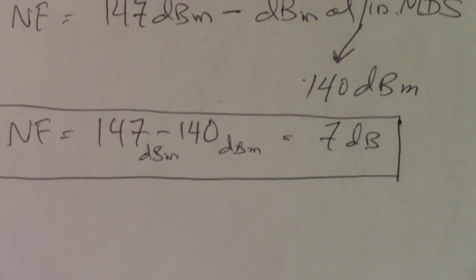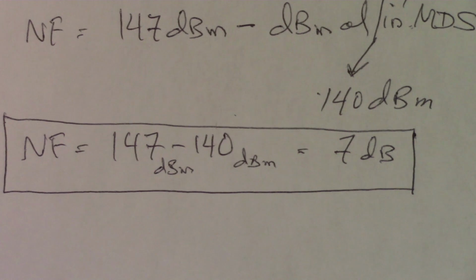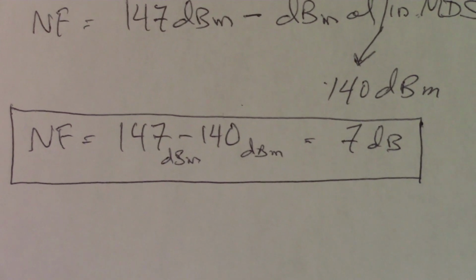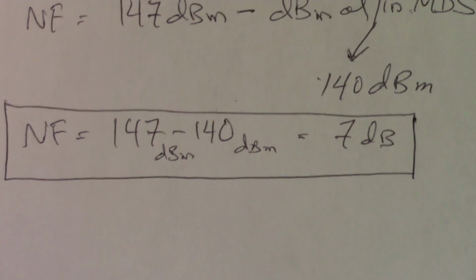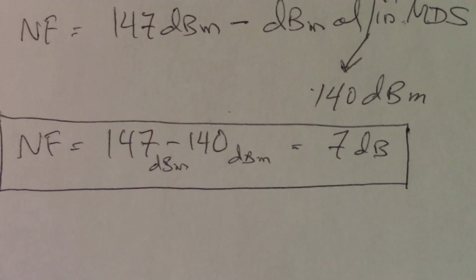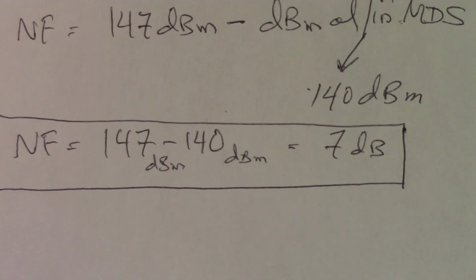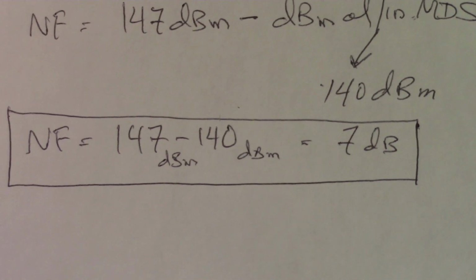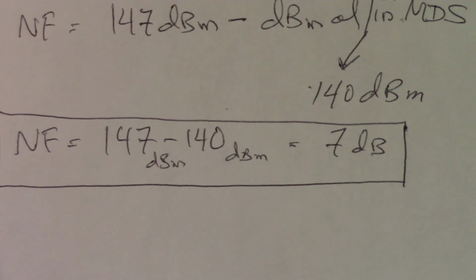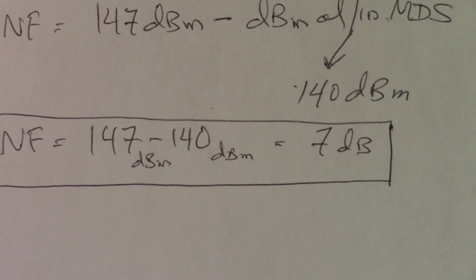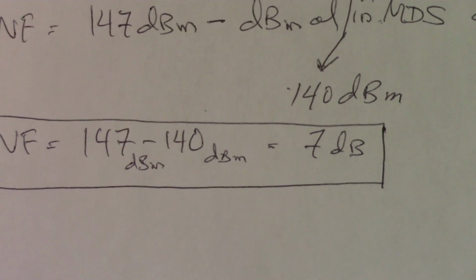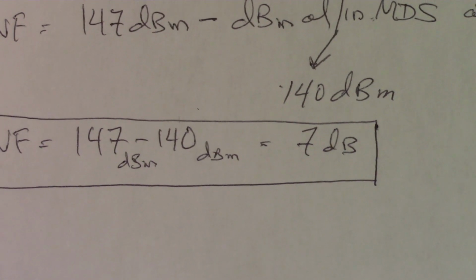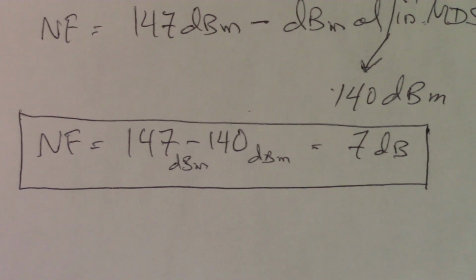Notice that if you were to add an LNA in front of this, let's say you had a LNA that had a noise figure of 3/4 of a dB, it would help substantially this receiver detect very weak signals for moon bounce, EME, or meteor scatter, things like that.